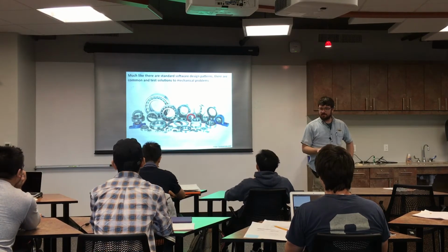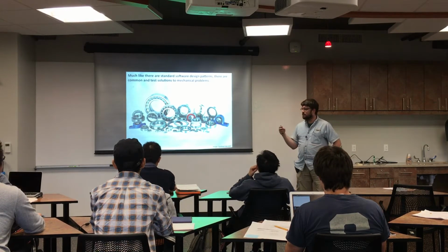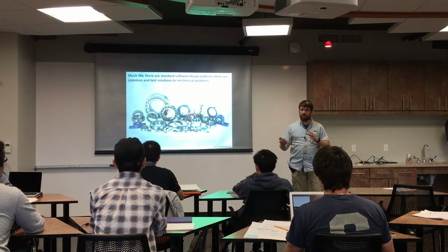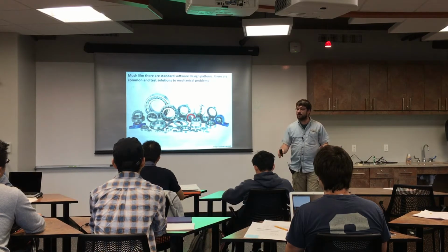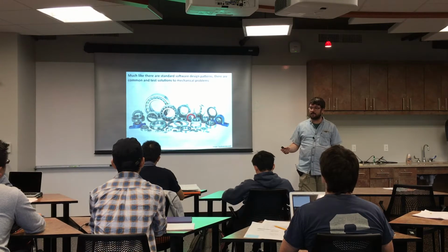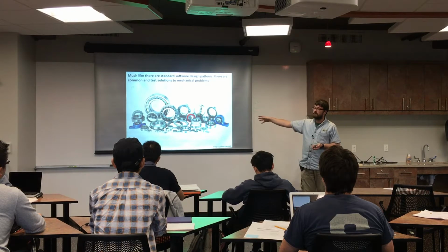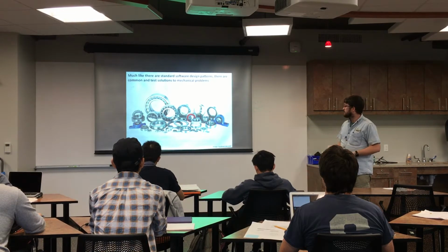So we've talked about software design patterns before, and in mechanical engineering, well, in all of engineering, there's something very similar. We use these well-tested patterns of designing and doing things. You need to move something, you need to translate it in one axis. Okay, here's 3 or 4 ways that we know how to do that. They work well. We've used them in devices for 50, 100 years, and we know where the failure points are. We know what their advantages and disadvantages are. So we'll look at some of those mechanical design patterns, for example, using bearings to support things that need to rotate and have low friction and low wear. And we'll talk about those, for example.